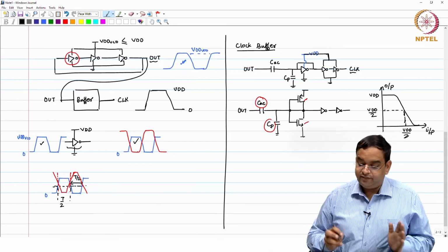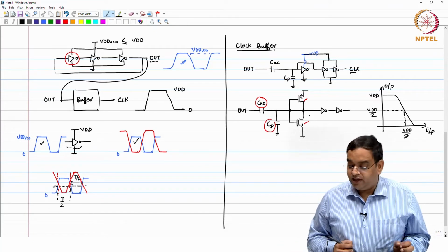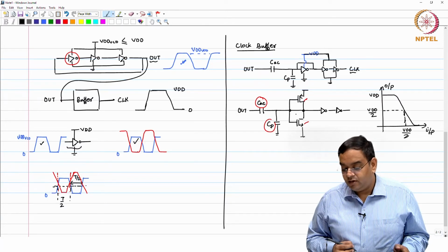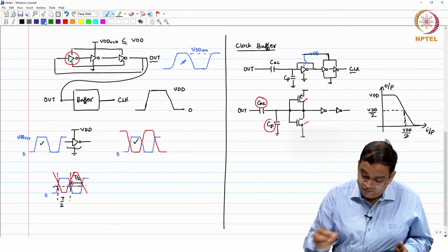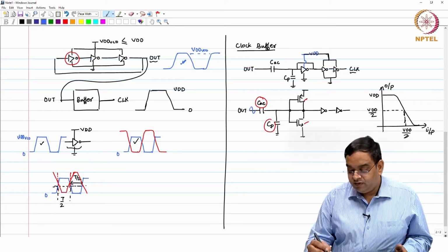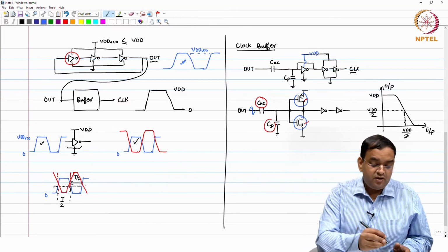Okay. So, you choose the PMOS and NMOS sizes accordingly. This is a nominal operating point, and you get this capacitor. When any frequency comes in here, what is that signal going to see? That signal is going to see a loading because of the PMOS and NMOS current sources here and CP both.